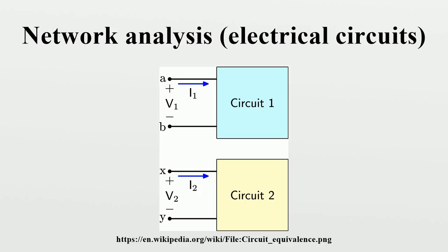Definitions. Equivalent circuits. A useful procedure in network analysis is to simplify the network by reducing the number of components. This can be done by replacing the actual components with other notional components that have the same effect. A particular technique might directly reduce the number of components, for instance by combining impedances in series.